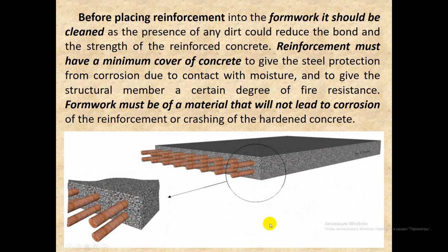Before placing reinforcement into the formwork, it should be cleaned, as the presence of any dirt could reduce the bond and the strength of the reinforced concrete.